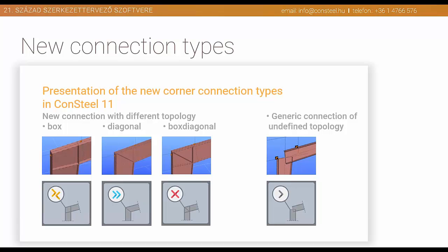The additional diagonal stiffener doesn't allow the web, the corner itself, to distort, and therefore it is completely unable to transfer any sort of kinematic displacement of same sign or reverse sign to the other element. It will act as a sort of warping support. It will stop the warping effect from being transferred from one element to another.